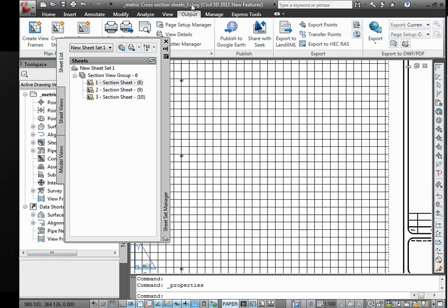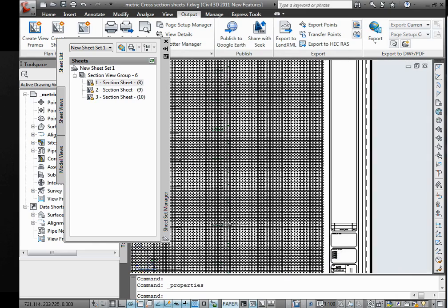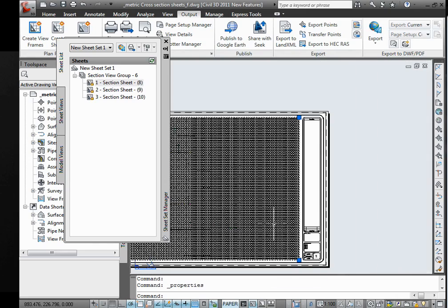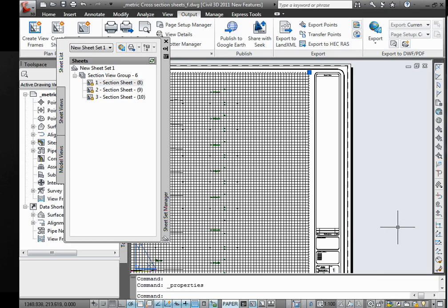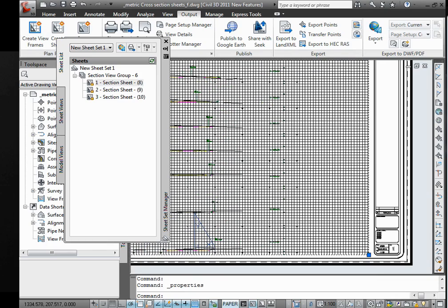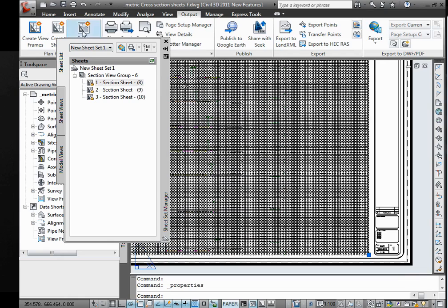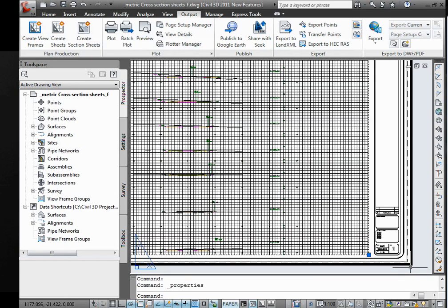So this new functionality in Civil 3D 2011 provides a wizard-driven approach that automates the generation of cross sections. Enhanced sheet styles and labels provide additional controls over the appearance of the cross sections. In addition, linear objects and blocks can now be projected to multiple cross sections in a single operation, which can help save time when compared to doing each cross section individually.